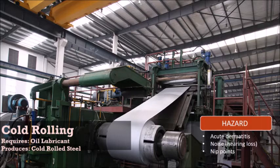The raw material is thereby passed through rollers below the recrystallization temperature of the relevant type of steel or stainless steel. The crystalline structure is also deformed. Additionally, the grain size is reduced, resulting in increased strengthening. The steel must be passed through the rollers several times to obtain the level of thickness or the shape required. This can take longer than the hot rolling process. Cold rolling requires oil lubricant and then produces cold rolled steel. The hazards of this process are acute dermatitis, noise, and nip points.